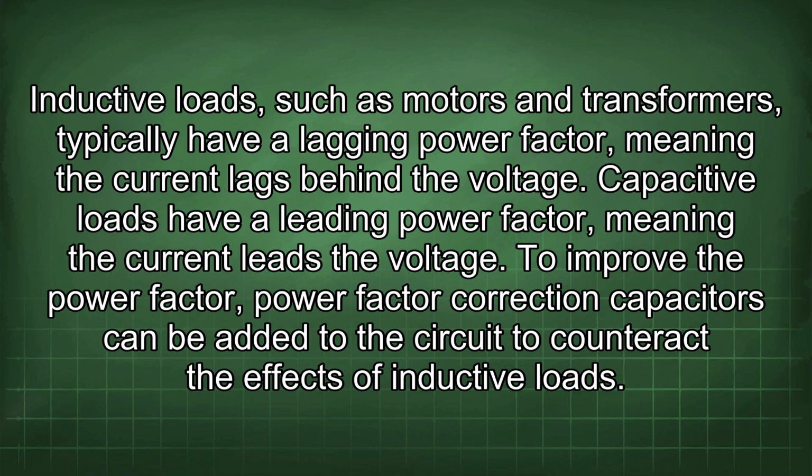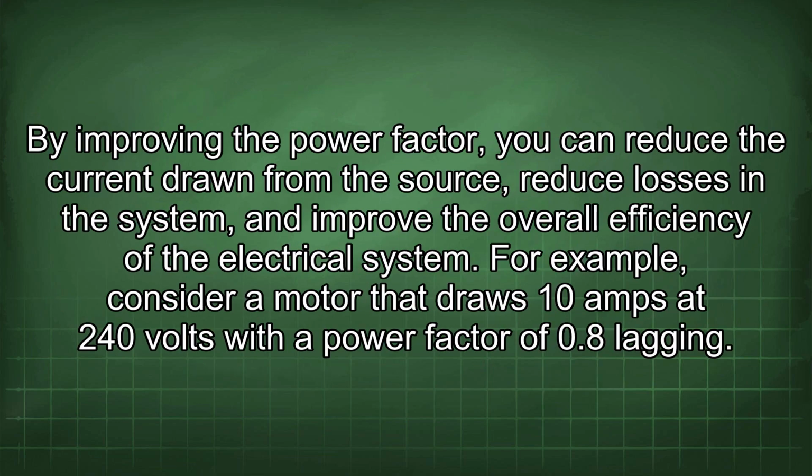To improve the power factor, correction capacitors can be added to the circuit to counteract the effects of inductive loads. By improving the power factor, you can reduce the current drawn from the source, reduce losses in the system, and improve the overall efficiency of the electrical system.